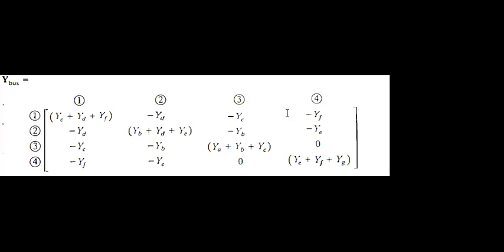So this is the summary of the admittance information in matrix orientation, and that is known as the Y bus of that circuit, from the admittance diagram of the circuit. The admittance information will generate the Y bus matrix based on the KCL concept, or the nodal equation concept, for different nodes.